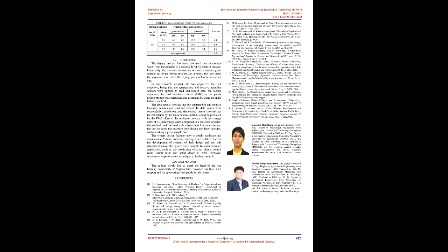According to the experiment conditions, the velocity of hot air flow was adjusted to 3 levels, for a study of the estimation of moisture reduced in the drying process. Between the beginning and the completion of the drying process, the user took a grain sample out of the dryer, then measured moisture using the moisture MC detector. A grain sample was taken 5 times to measure the moisture, using the average value. The standard deviation was considered, as shown in Fig 9 and Table 4, which compare the FMC from the moisture detector with the estimated value.